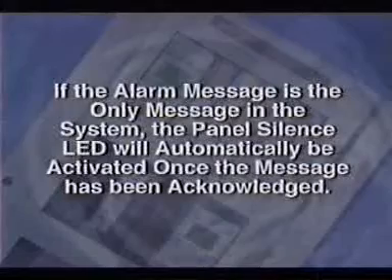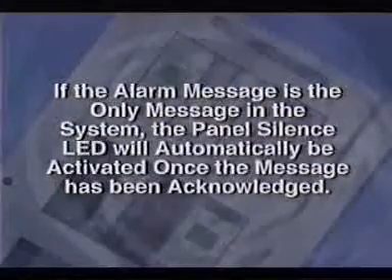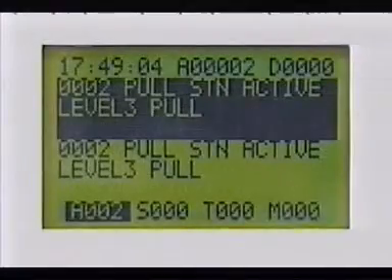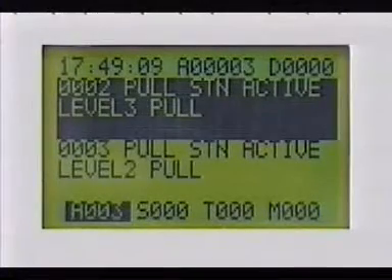If the alarm message is the only message in the system, the panel silence LED will automatically be activated once the message has been acknowledged. If another initiating device goes into alarm, the internal buzzer will sound again and the new message will appear.